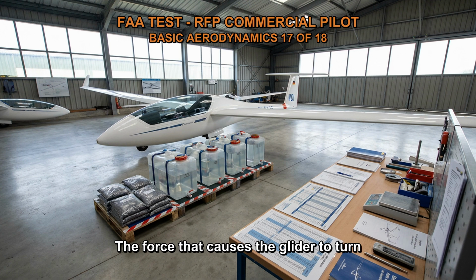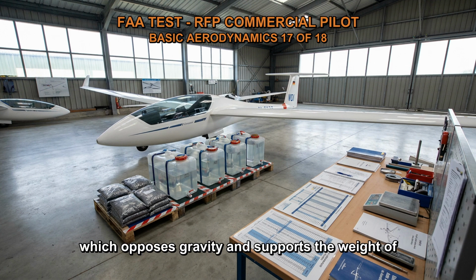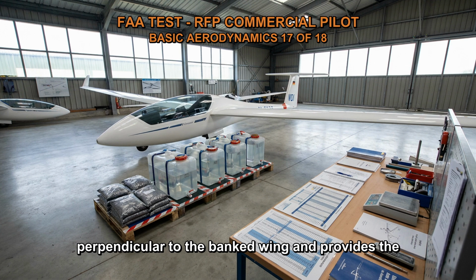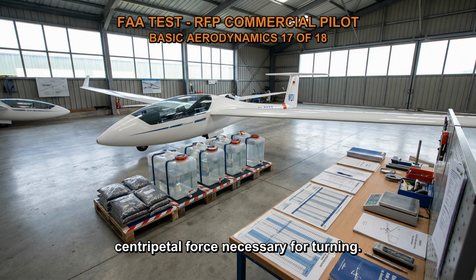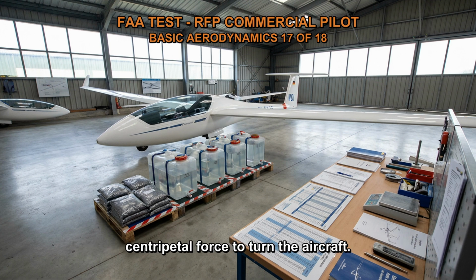The force that causes the glider to turn in flight is the horizontal component of lift. When the glider is banked, the lift force is divided into two components: the vertical component, which opposes gravity and supports the weight of the glider, and the horizontal component, which acts perpendicular to the banked wing and provides the centripetal force necessary for turning. By adjusting the bank angle and controlling the distribution of lift, the glider can generate a horizontal component of lift that creates the necessary centripetal force to turn the aircraft. This allows the glider to change its direction without relying on engine power.